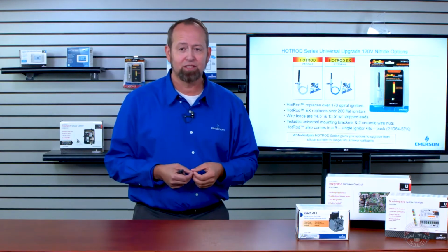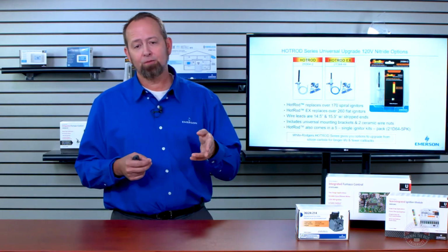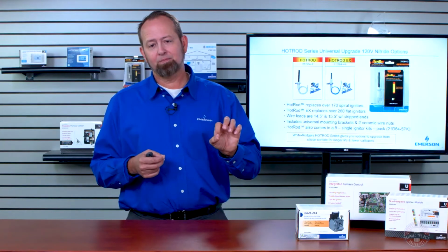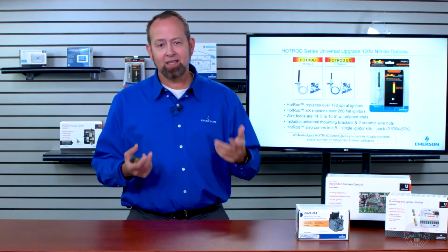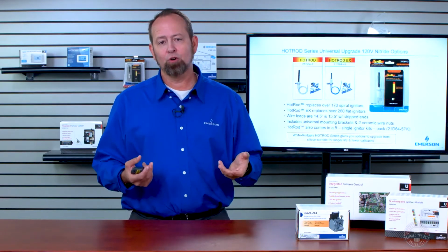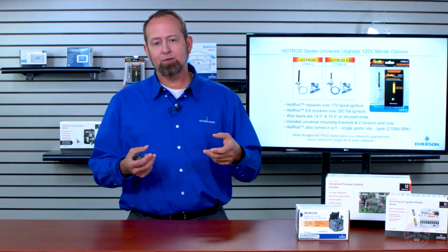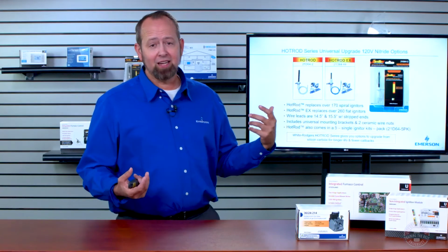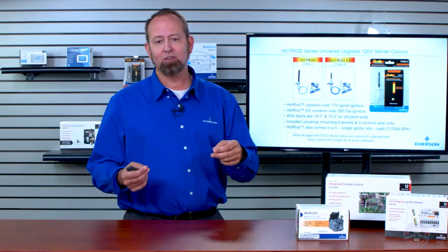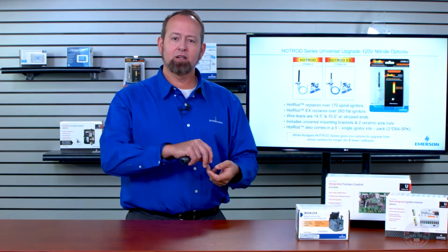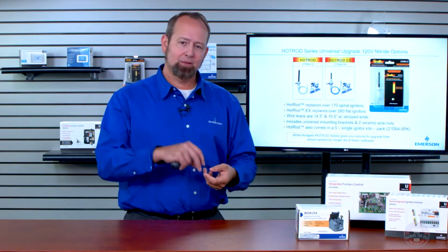It makes no difference either way. If you cut that plug off of the old igniter, in the future, if there was any work or repair done needing to pull the burner or the igniter out of the furnace, you have that plug to unplug rather than deal with trying to take off wire nuts and put them back on.